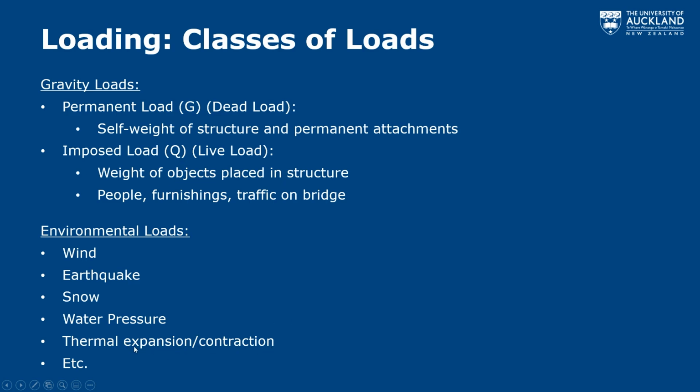Thermal expansion and contraction. So this is really a big consideration for bridges, which are outside. They heat up all day. They're long. They will expand out. And then at night they contract in. So as they're expanding out, they're going to push against the abutments of the bridge, and that will induce some compression force.